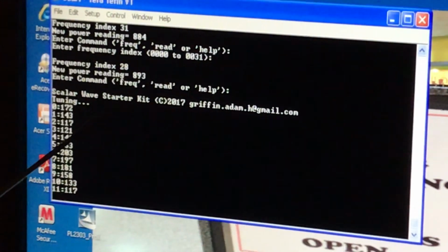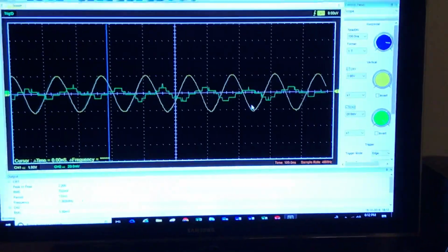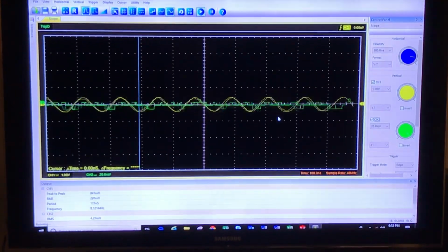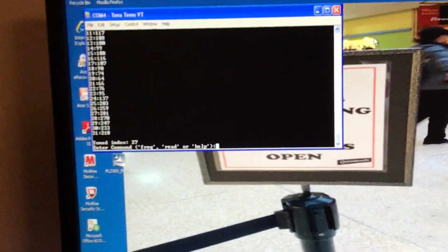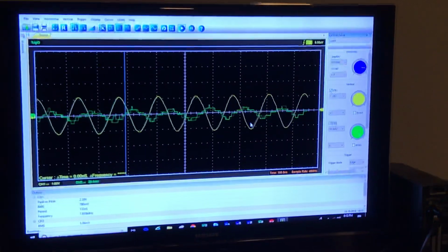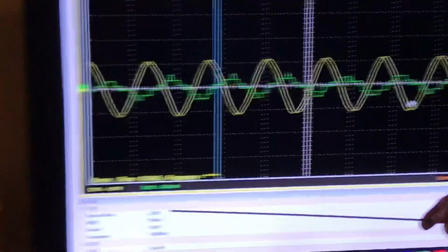You can see here on the display that the transmitter is talking to the computer, telling it what it has done and what it has learned. What the transmitter is actually programmed to do is change the frequency applied to the excitation coil 32 times, and each time sniff and report the maximum power it feels was delivered to the receiver. What we just saw is the transmitter's automated power readings. It takes 25 seconds to run through its tests and select a frequency based on that learning.